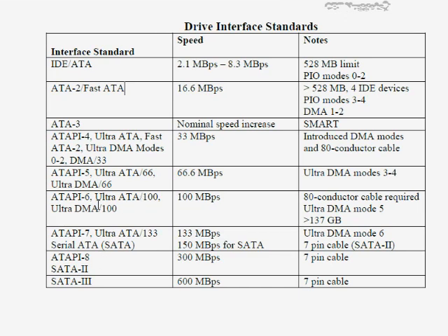Also, anything that does not say serial ATA on this chart refers to another standard called parallel ATA, which I've already referenced many times before. The parallel ATA is what really describes that whole master-slave and cable select configuration. And it's called parallel, by the way, because the data travels in parallel lanes to and from the hard drive, whereas serial ATA is more in a single file line. Parallel ATA also is what does not require termination and does not have device IDs.